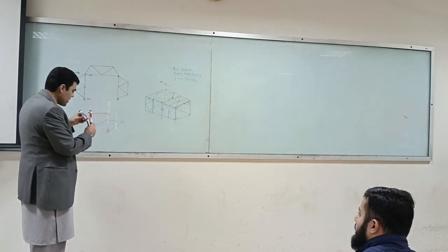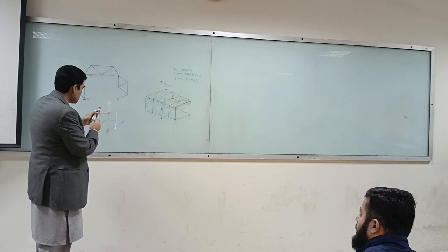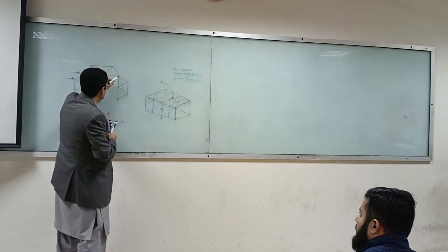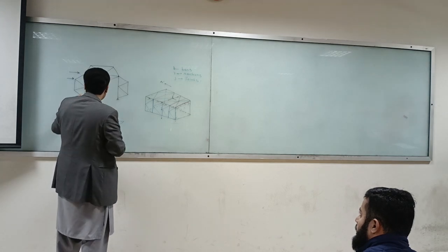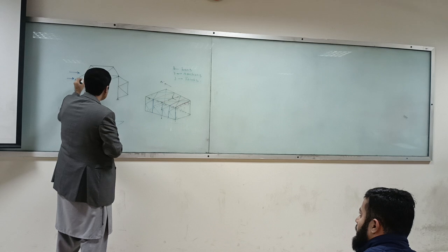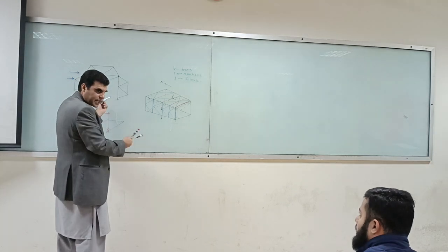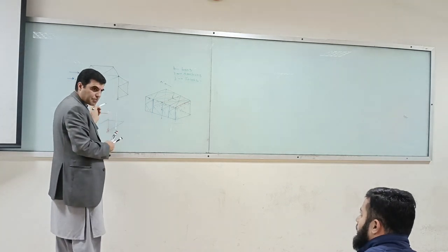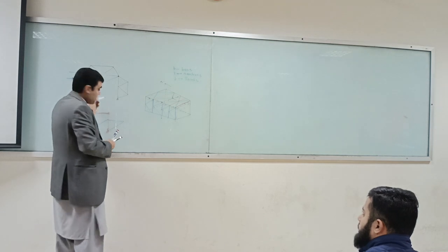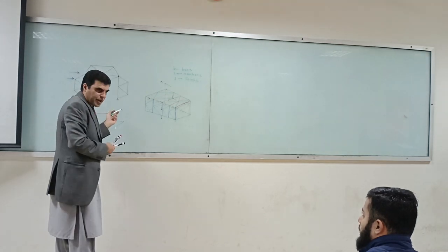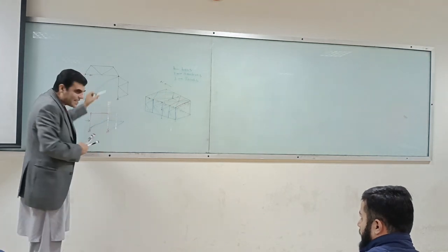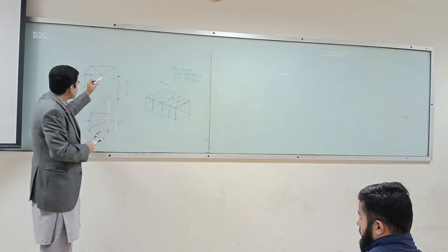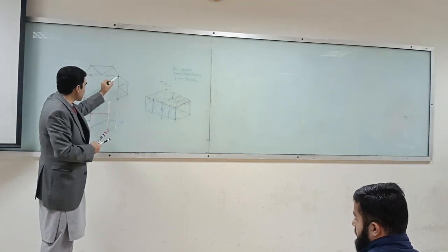So what we can do is, we can provide a bracing over here. Imagine this can be a cord or it can be a brace. Just one brace you can provide. Or you can provide an X brace. But once you provide the X brace, what will happen? This load can now be taken.